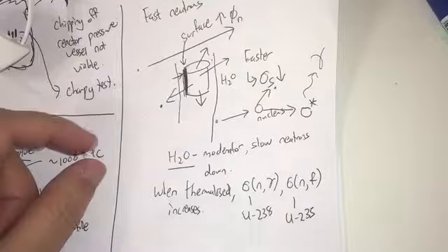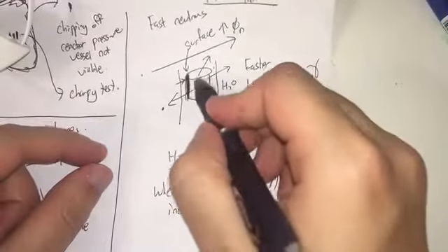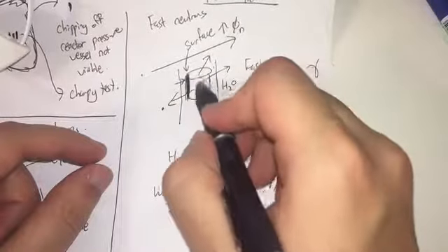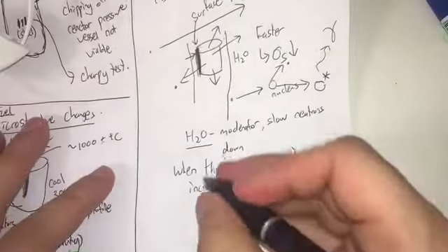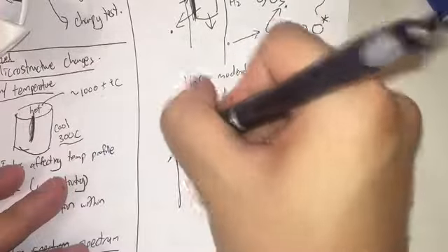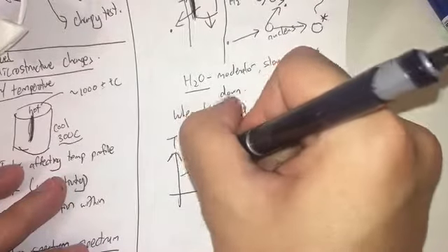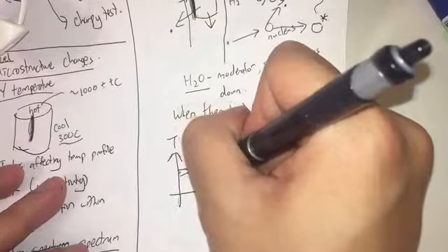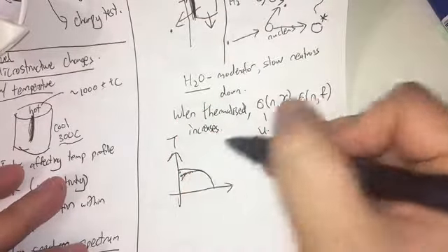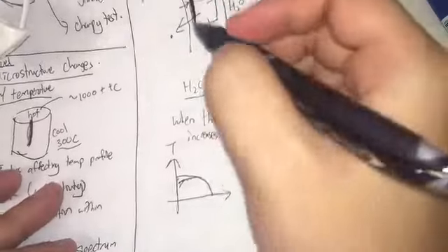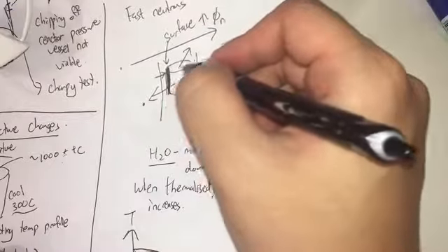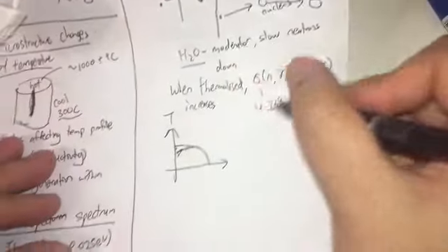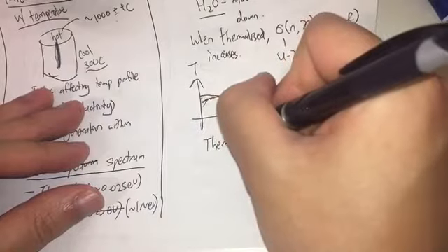Meaning to say that the fuel consumption rate and the heat generation rate near the center is lower. And that means for our temperature profile, okay, the center is still the hottest, but maybe it will not be as hot as compared to a fuel pellet that has a very even kind of heat generation. So let's do a thermal.